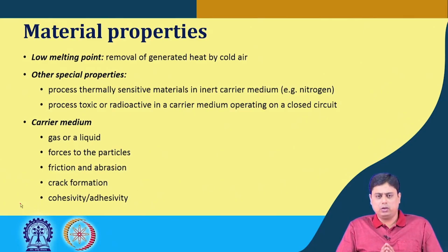So, such kinds of parameters we have to think about in deciding the use of appropriate size reducing equipment. We have to also think of the forces on the particle while it flows with the carrier medium. We have to account for the friction and abrasion while it flows, because we will see that during transport in fluidic media, the solid particles create a lot of friction and abrasion.